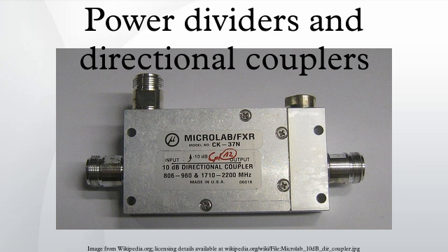However, since the devices are essentially identical, the reflection coefficients from each device are equal. The reflected voltages from the FETs are in phase at the isolated port and are 180 degrees different at the input port. Therefore, all of the reflected power from the FETs goes to the load at the isolated port and no power goes to the input port. This results in a good input match.